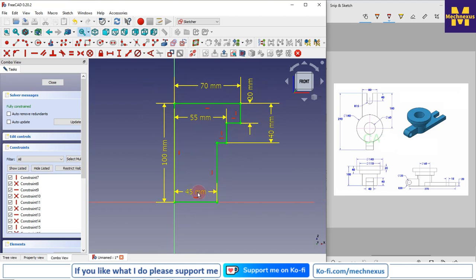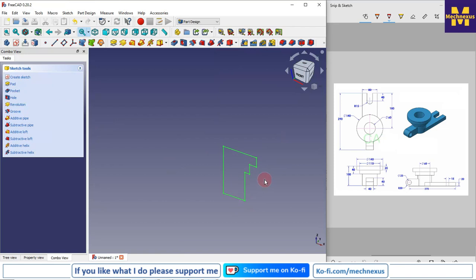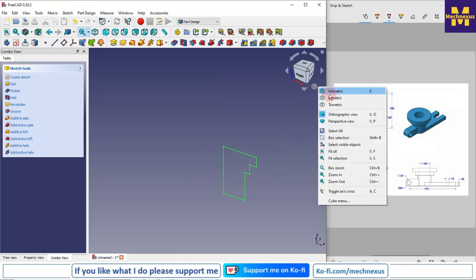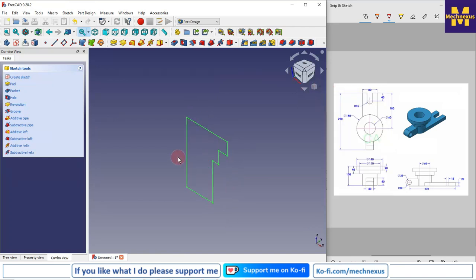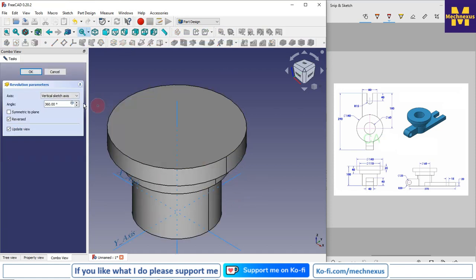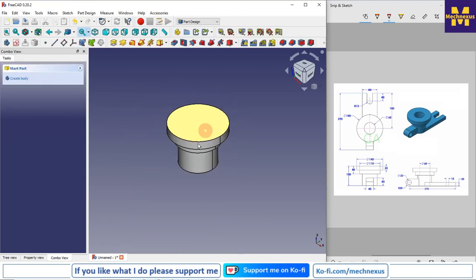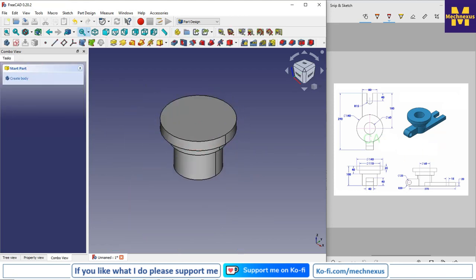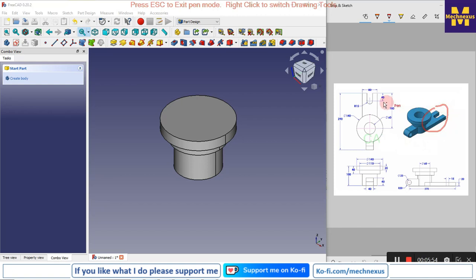So our sketch is fully constrained, and now I will come out of the sketch and go to the isometric view, and here I will click on this revolve feature, so you can see that it automatically took the axis. Now I will say OK, and now we will draw this front feature here, whose dimension is given here.